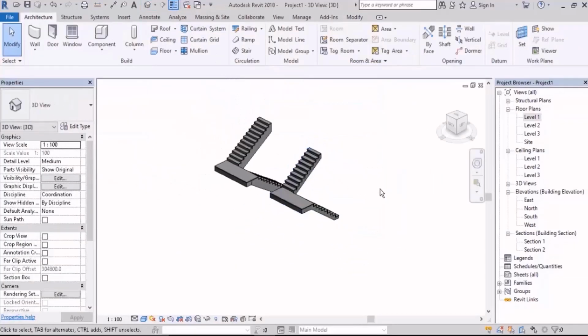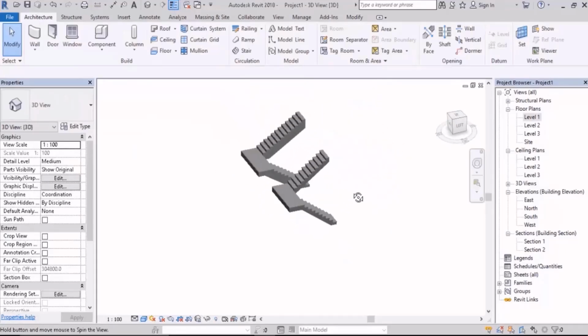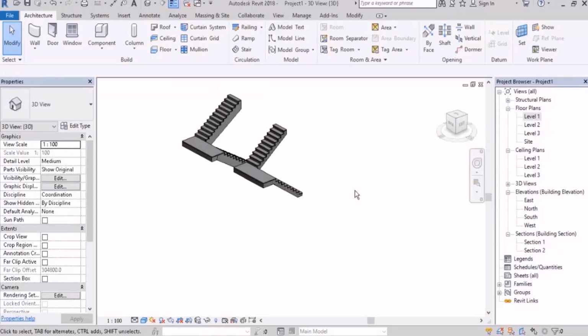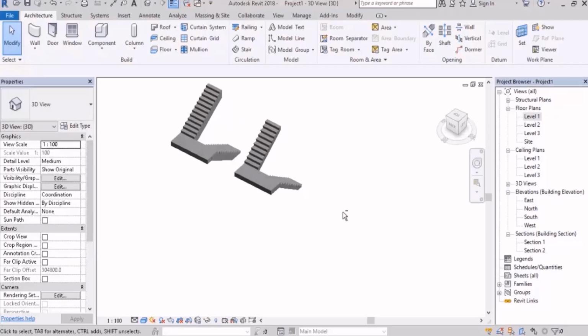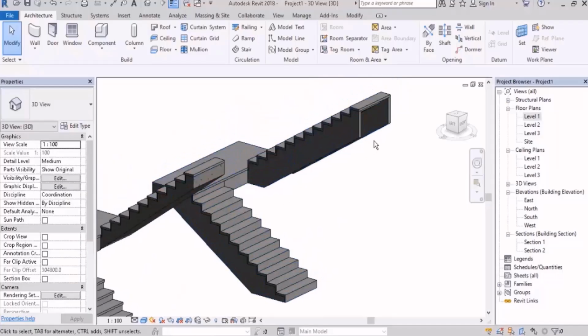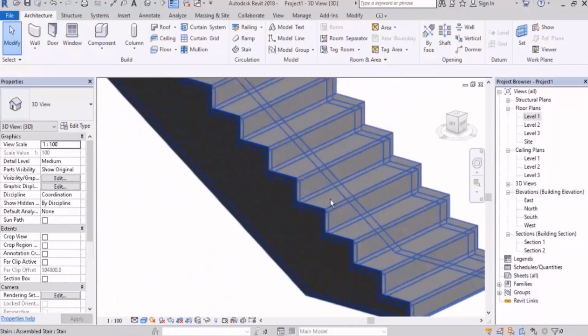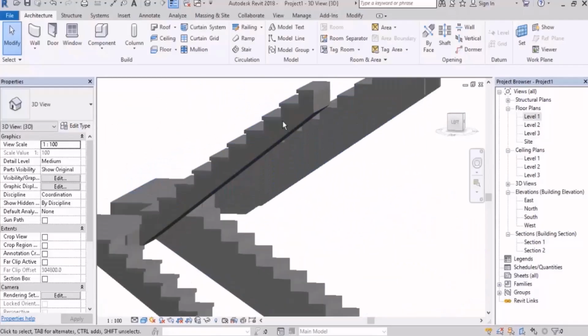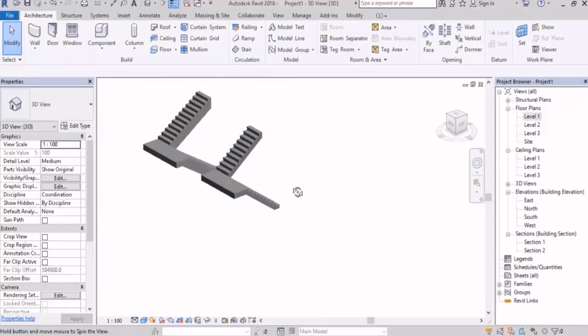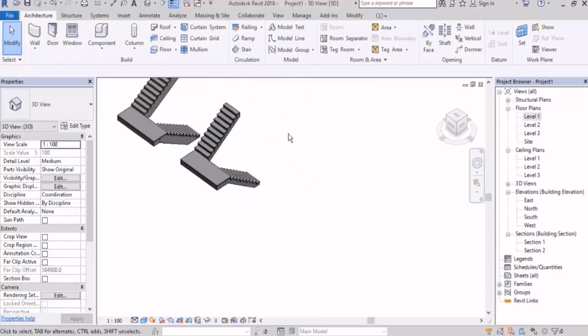We have the same process in the assembled stair. Let's do it here too, as a review. I go to the section, I select it, click on edit and then select the last ramp. You see, it will not be something good, it will not be something perfect. If it were up to me, I would tell you to do this all the time. Always inactivate the end with riser. So go to the last ramp and inactivate the end with riser. And that's it. And here it informs us too.